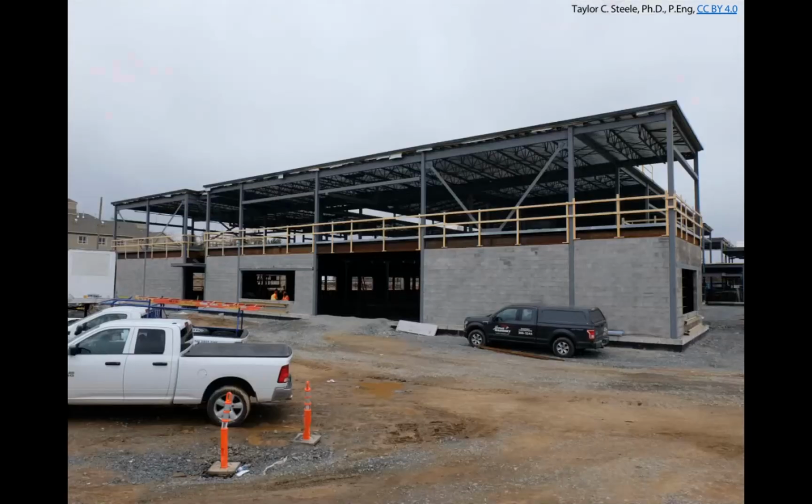So I showed you this picture the first day, and this was that school that was built recently on the north side. I had given this as an example of a steel frame building that was relatively simple, but I also gave it as an example of a structure that would have something like tension-only bracing. We've got a brace here and a brace here, and if we've got loads acting in this direction, then we're going to have the brace that wants to push. It's not going to be able to push because it's flimsy. It has like a resistance of 2 or 3 kilonewtons.